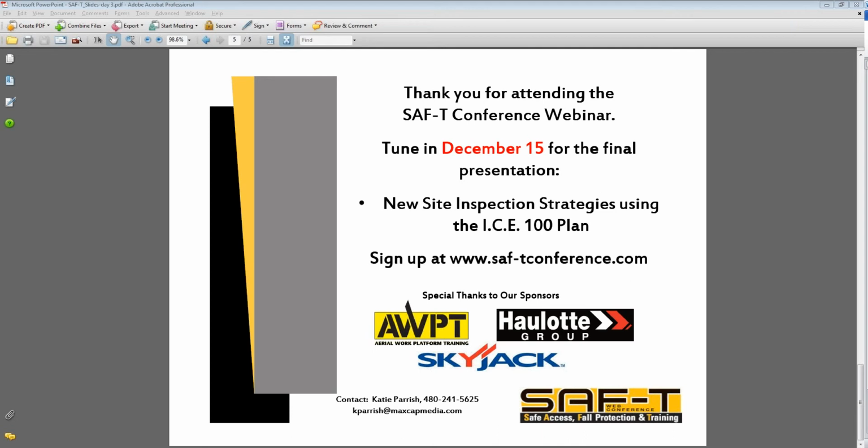From a safety perspective, how safe is it to drive while the machine is elevated? I think as long as the ground conditions are suitable, and you've done that kind of risk analysis, there are a lot of factors in that question, but if the ground conditions are suitable and there aren't any elevated obstructions that you are potentially going to run into, or electrical lines or whatever, as long as the lift is rated to be operated while elevated, it is not a risky proposition.